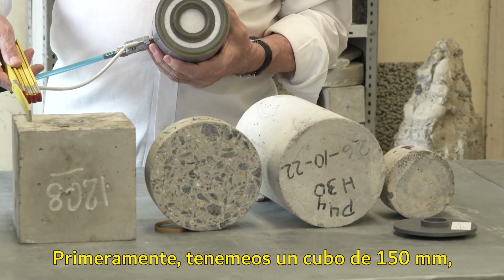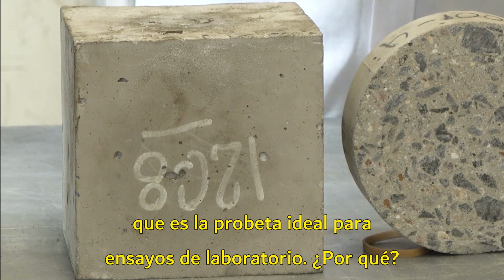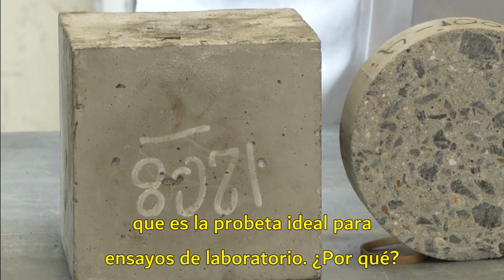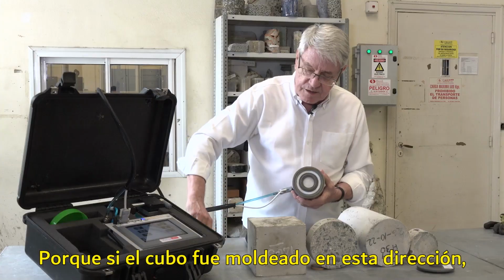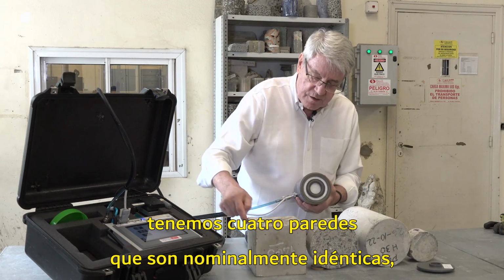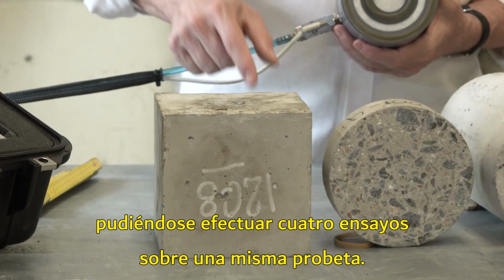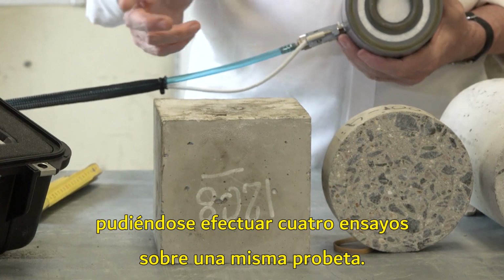First of all, we have a cube, 150 millimeters cube, which is the ideal specimen for laboratory test. Why? Because if the cube was cast in this direction, we have 4 walls that are nominally identical, so we can run 4 tests on the same specimen.